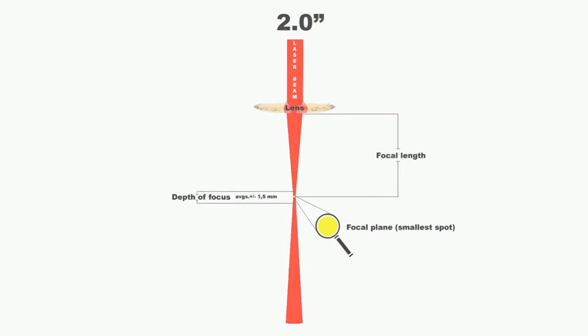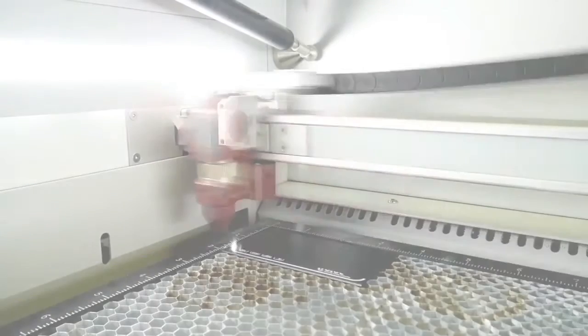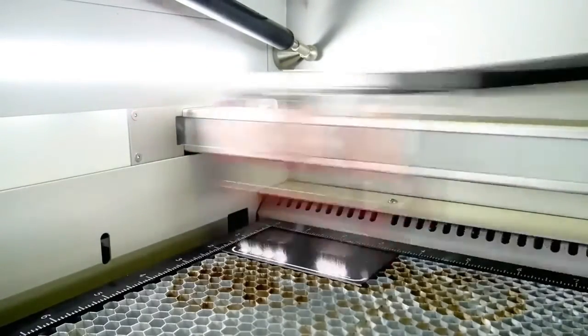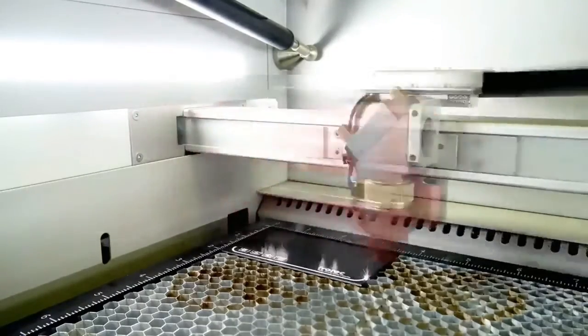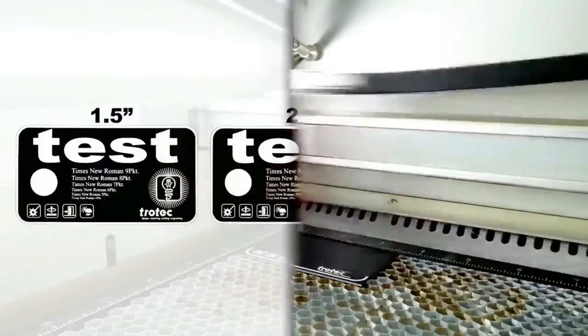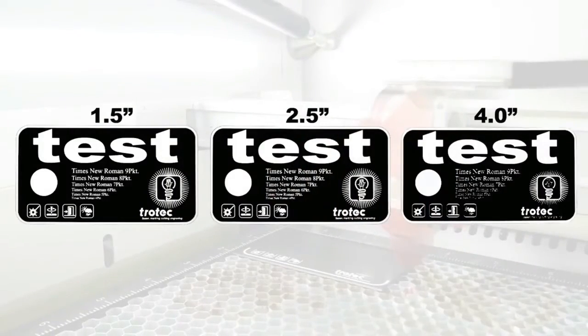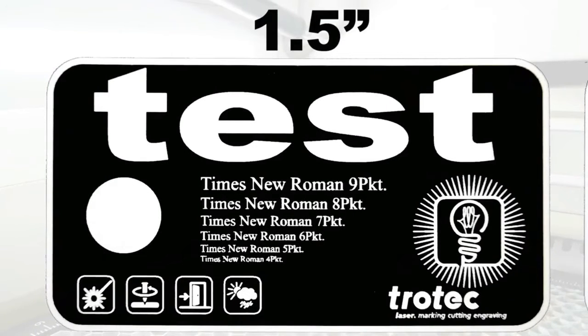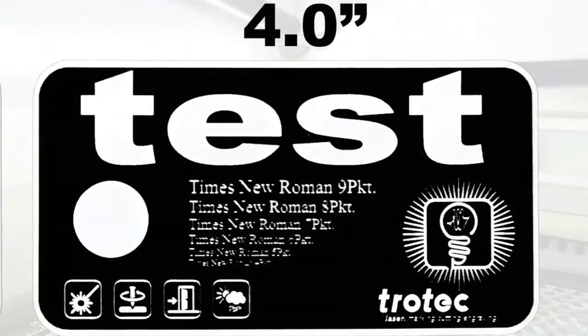For this first example, we will engrave a Trotec test graphic using the 1.5, 2.5 and the 4-inch lens on anodized aluminium. So here we can observe the results on 3 pieces, and we can see that the 1.5-inch lens is able to produce the clearest engraving in the areas where we have the smallest details. In contrast to the 4-inch lens test here, it doesn't look very good.